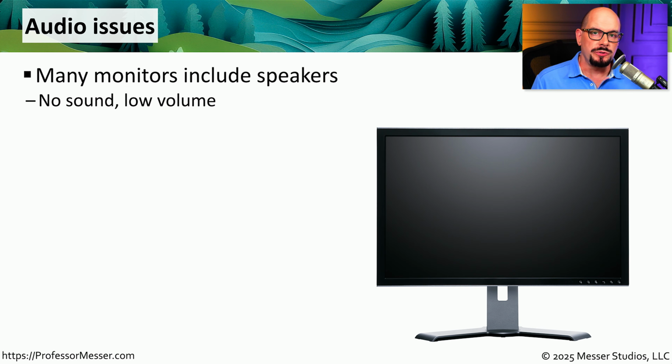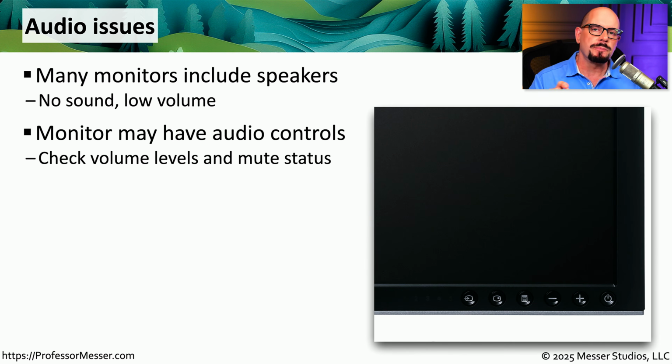Many monitors we use today are for more than just video output. Many of these monitors have speakers inside of them, and we can use them as audio output as well. If you're having a problem getting any sound out of the monitor or the volume levels are very low, you'll probably want to do some troubleshooting. If the monitor has speakers, then it probably also has a volume control setting, so you may want to check that volume control to see if it's turned down or if someone may have muted the speakers entirely.